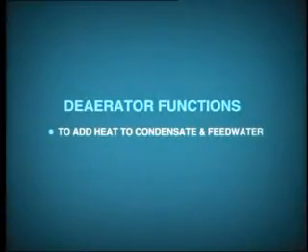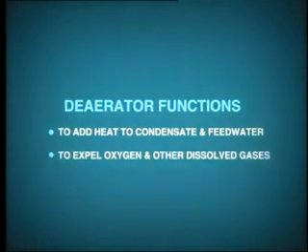Okay, now let's turn our attention to the open heater in this system, that is the de-aerator. The de-aerator actually has two functions: to add heat to the condensate and feed water to improve cycle efficiency, and to expel oxygen and other dissolved gases from the boiler feed water.